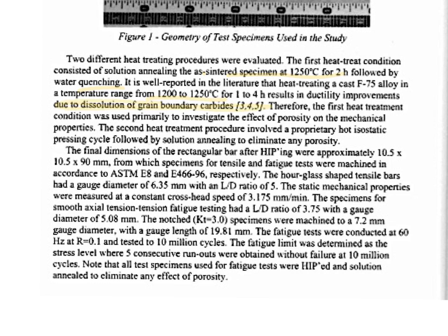Okay, so right away we're talking about what happens to what's at the grain boundary and how, as it sits at high temperature, those carbides can diffuse away through the lattice. All right, and that is the dissolution process, based on diffusion, not based on melting, but diffusion of these things away from the source in the microstructure.